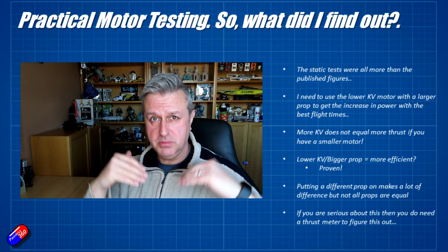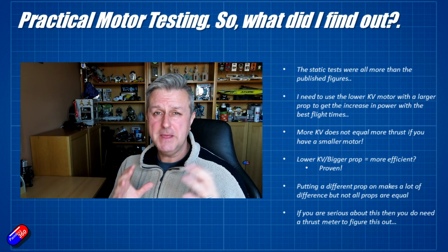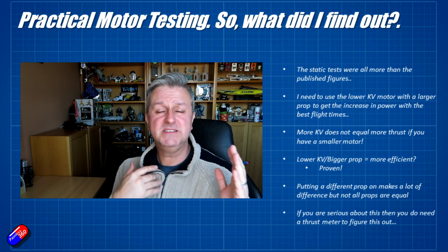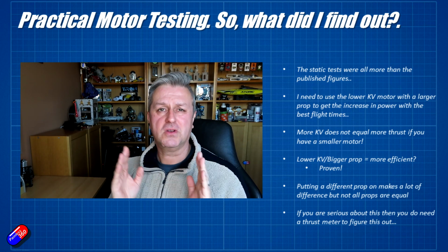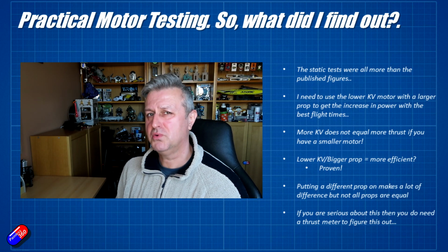Nice that T-Motor actually published that data. I wish more motor manufacturers did it. It makes it an awful lot easier to see the thrust that you're going to get and to do that basic calculation that I do. It's the weight of the model, figure out how much thrust I want, and then I can look it up on a table and buy that motor and prop.